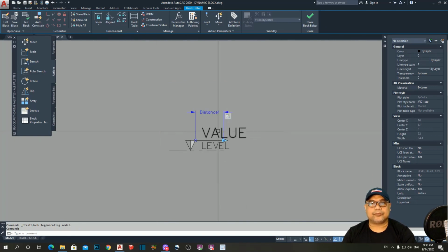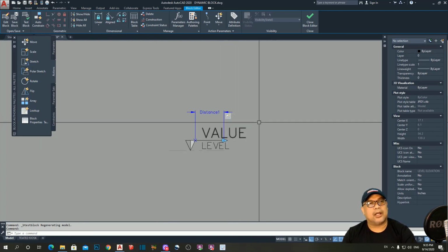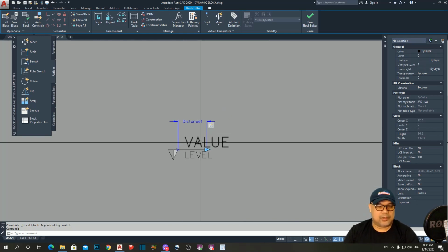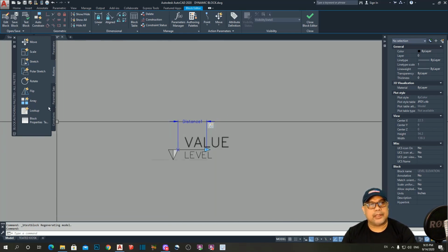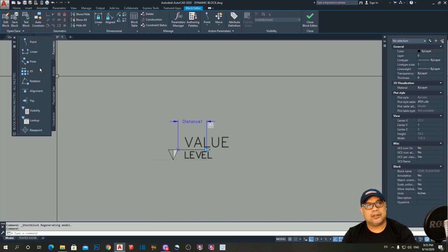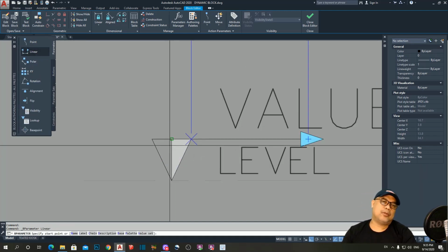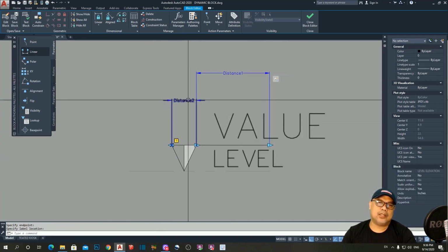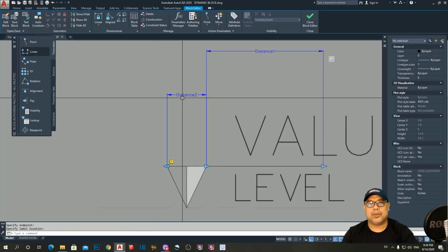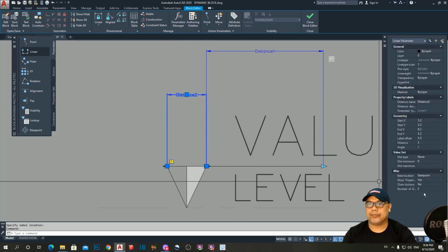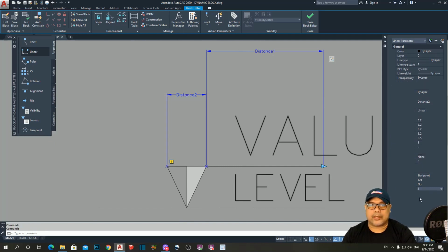Then let's do the second feature, the scale. So same command, go to parameter, linear, then this time we have to place it here, and AutoCAD automatically names this one distance 2. Again, we have to reduce the grip point. I have to do it here again, 1.